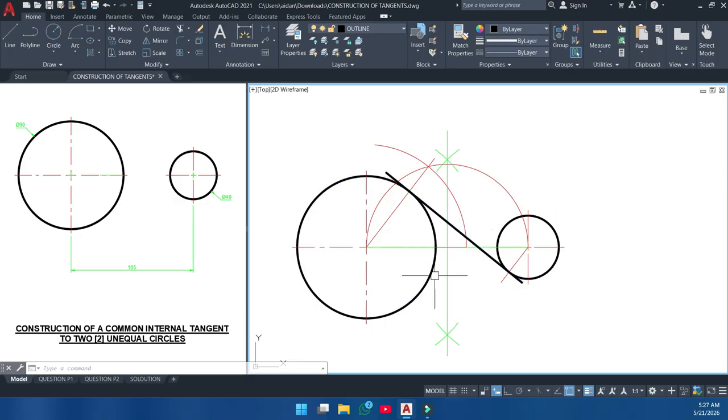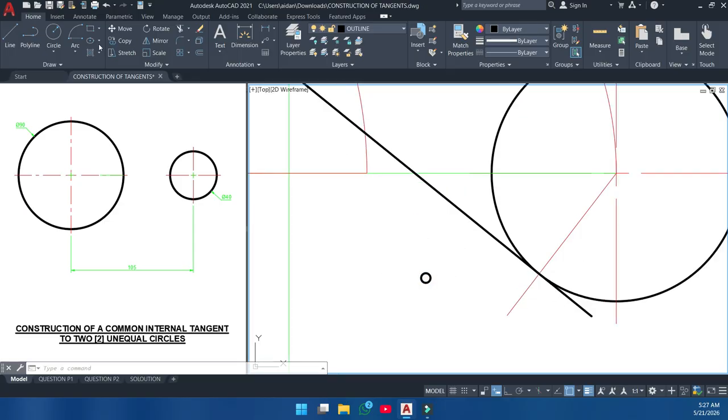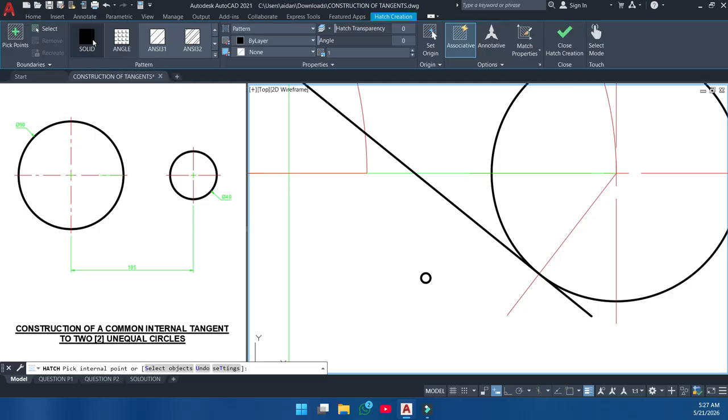The next step would be to label the figure. Alright, you can identify these points here. This can be achieved by drawing a simple small circle. Select your radius command, draw a little circle here, use radius 0.75. This circle, zoom in on it, and using your hatching command, select, click solid, come back here on the circle and click once, press enter.